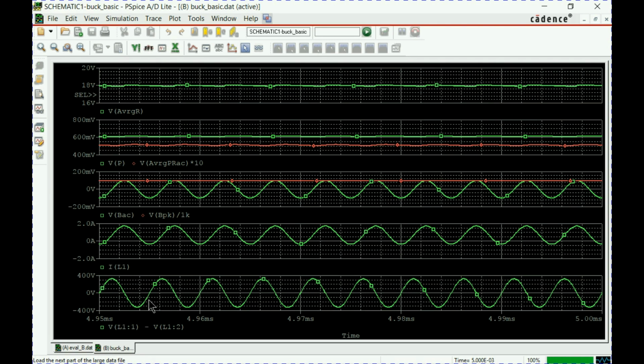Let's start from here. This is the voltage across the inductor. This is the current through the inductor. Well, the reason that there is a DC through the inductor is because of the initial condition. The question is, where do you start the voltage? If I would have started at 90 degrees, the DC would be 0, but this really doesn't hurt us